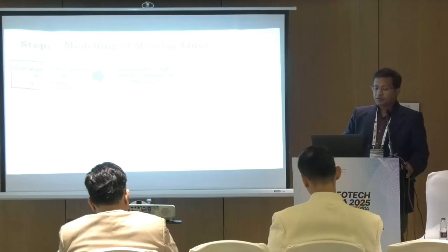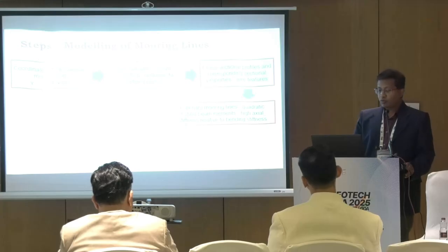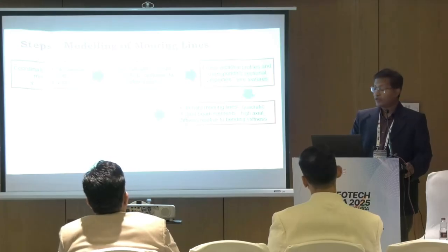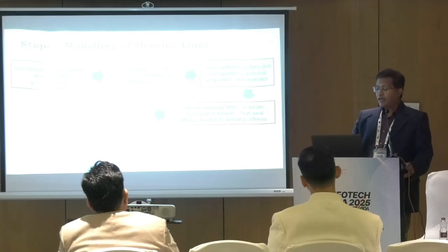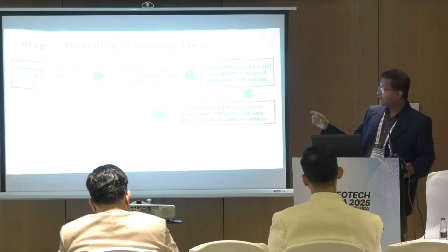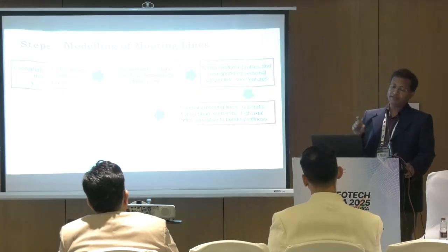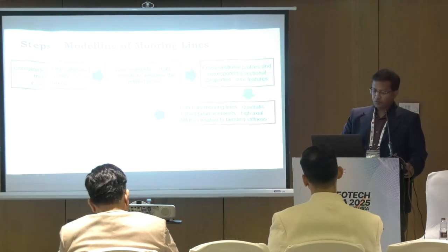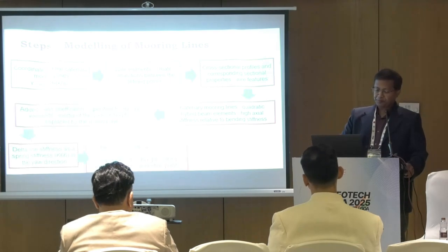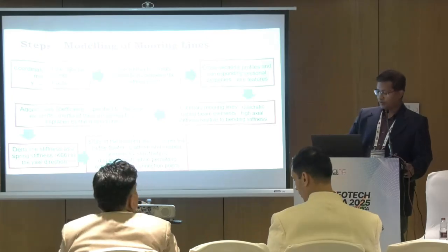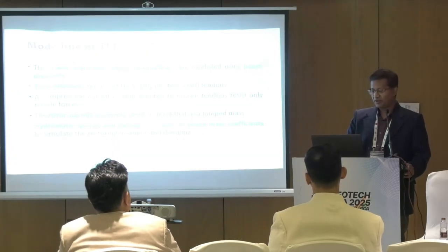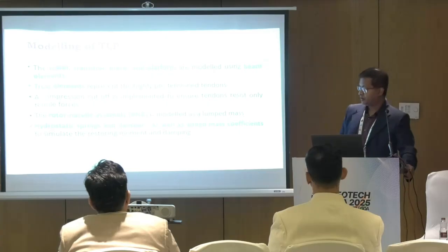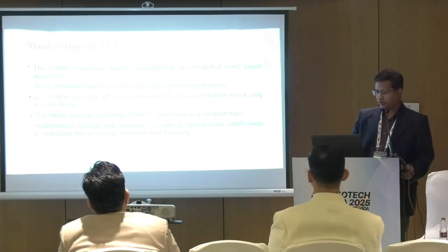Then you have to use the wire elements in Abaqus, and we use a very novel element which is developed, a quadratic hybrid beam element. It's a 3-noded element, each node has 6 degrees of freedom, and it has a very high axial stiffness compared to the bending stiffness, so that it can incorporate the flexibility effect of the mooring line. Using this concept, the system is modeled. But many other complexities are there which I am not discussing right now because of time limitations. More details are available in our paper, which will be published in the proceedings.